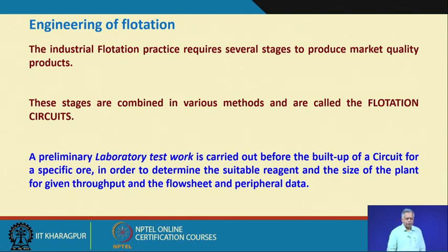How do I decide about this? To do that, first a laboratory test work is carried out, before the build-up of a circuit for a specific ore, in order to determine the suitable reagent. That is, I said that even for an iron ore you can have many collectors, but which collector should I use?